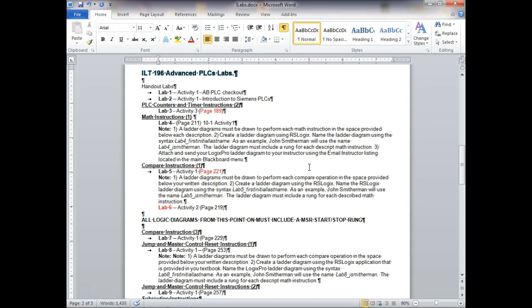Does that make sense? What you can do is load one of your N7 registers with the two numbers. We'll treat them like variables, even though it truly is not going to be a variable. If you load N70 with a number and you load N71 with a number and you never change that number, then those are technically constants, right? But you see what we can do? We can bring these from anywhere, right?